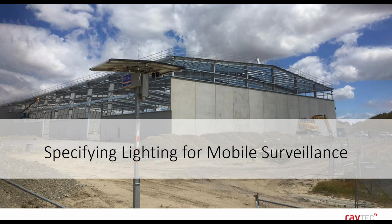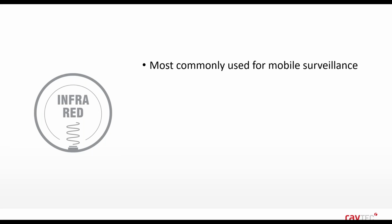So specifying lighting for mobile surveillance. First, let's have a look at what types of light there are. First of which is infrared. So I would say 80% of the mobile security towers that we've worked on use just regular 850 nanometers infrared. This is kind of the industry standard. It's what you see in the majority of camera integrated setups.